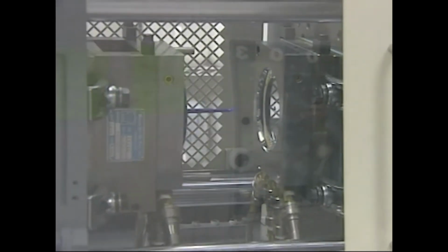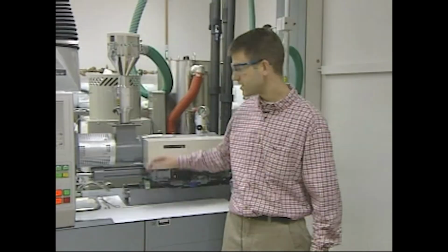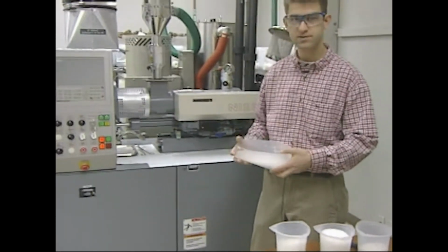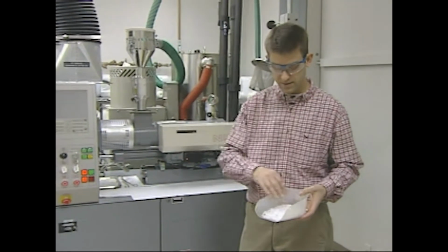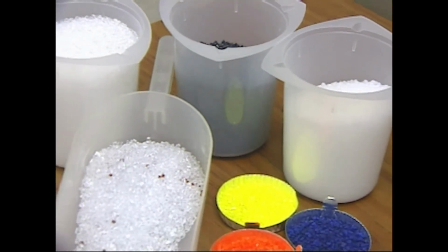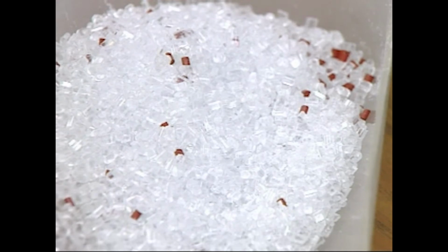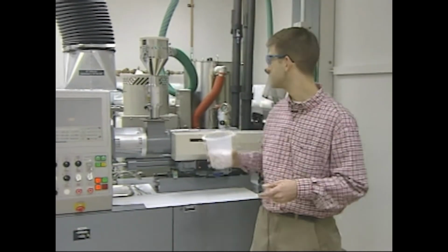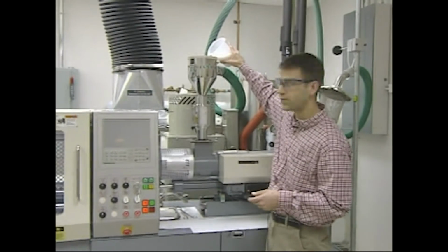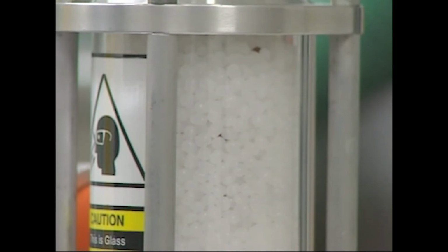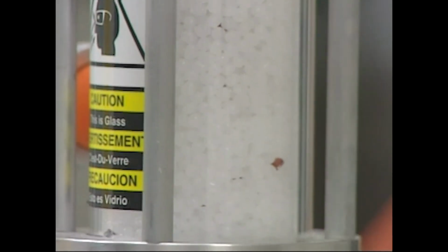It could be an inkjet cartridge or a printer cover, or it could be a plastic plate or a plastic fork. But anyways, how you work these types of machines is you use material such as this here. This is a plastic resin. It's just granulated plastic, and this particular one has some red coloring in it. You would take this plastic and put it in the top of the machine up here in the hopper. As you put it in, it is fed down into the throat of the barrel of this injection molding machine.